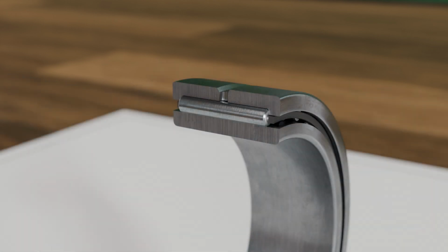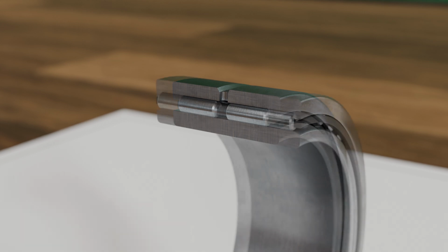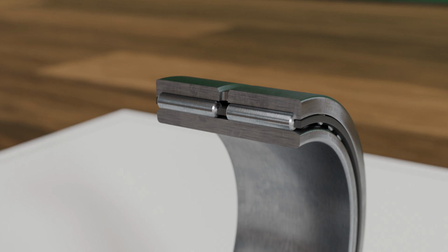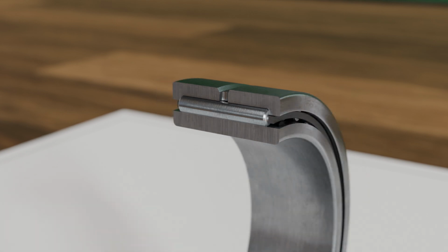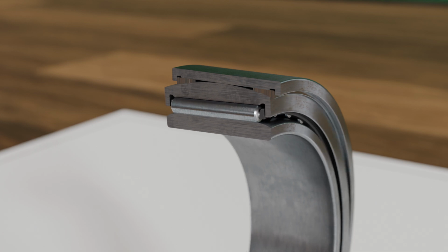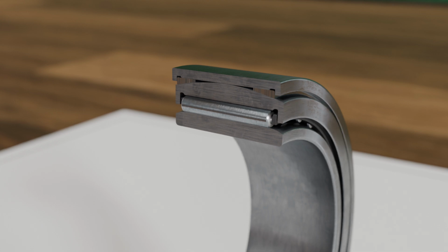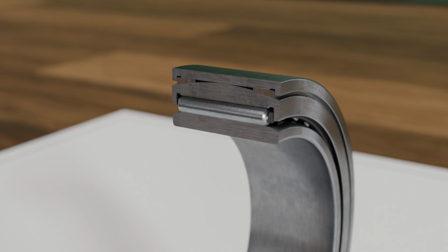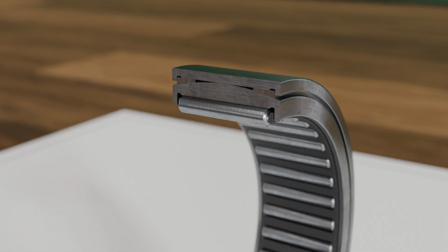Needle roller bearings are available not only in single row but also in double row designs, allowing for higher load capacity. Misalignment errors usually cannot be compensated by conventional needle roller bearings. However, special designs such as self-aligning needle roller bearings provide a solution. They feature a spherical outer ring and are installed in a correspondingly shaped housing seat. This design allows them to compensate for angular errors and misalignments of up to about 3 degrees, which can occur, for example, due to shaft bending. Such alignment needle roller bearings are available both without and with inner ring.